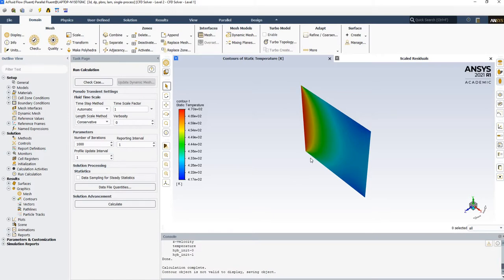If sunlight is passing through the air, not much of it actually changes the angle. But if it's too dusty or too thick, like if it passes through water, it does scatter a little bit. And if it is significant in your problem, you should not use the surface-to-surface radiation model. Instead, you should use the discrete ordinates radiation model.